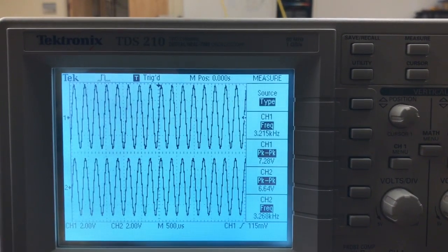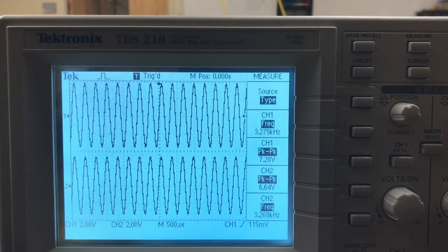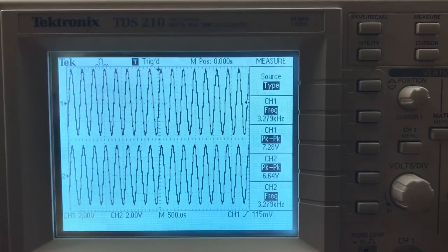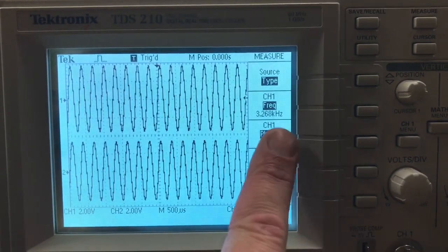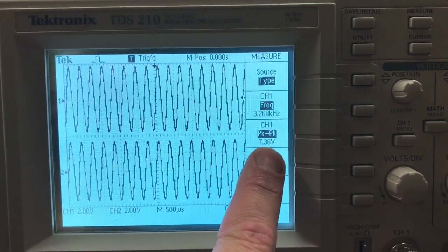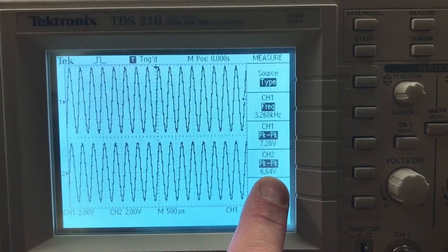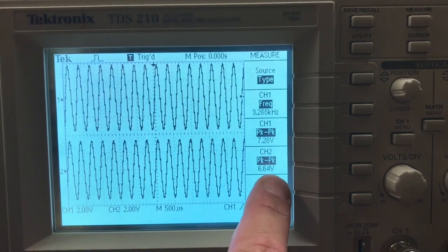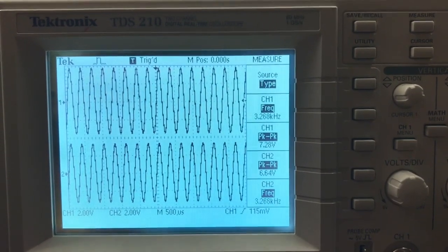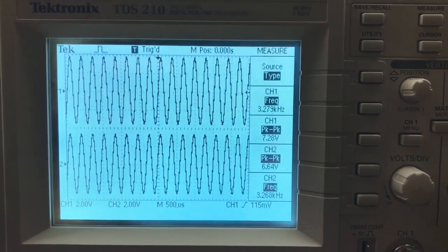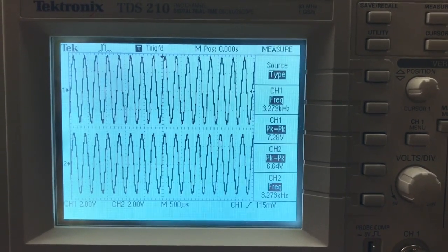But now you can see at high frequency, the voltage across the resistor is almost the same as the voltage across this circuit. You can see that's the function generator output, and that's the resistor voltage. So these get to be pretty close. That means there's only a small voltage across the capacitor. So the effective impedance of the capacitor is small at high frequency like this.